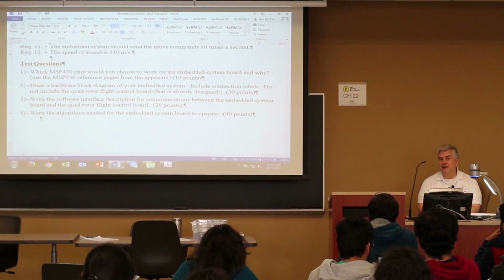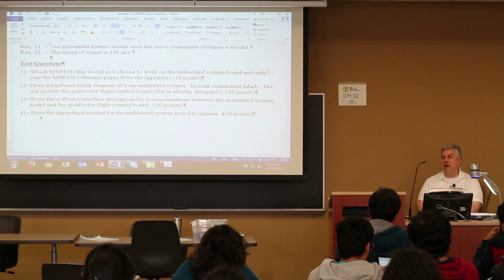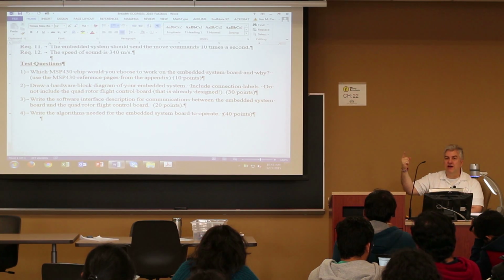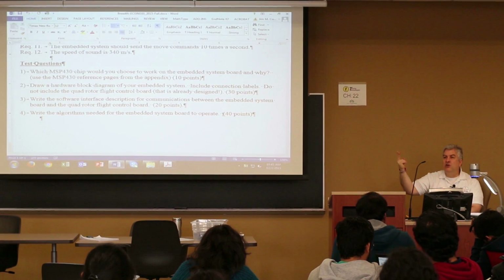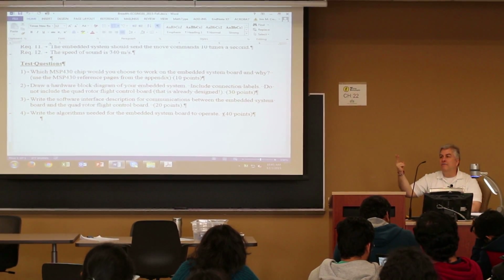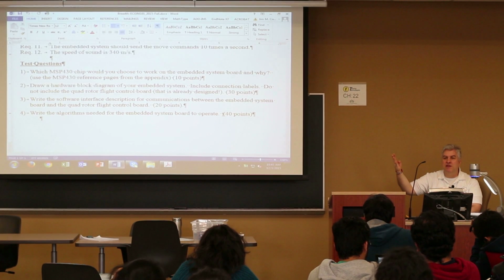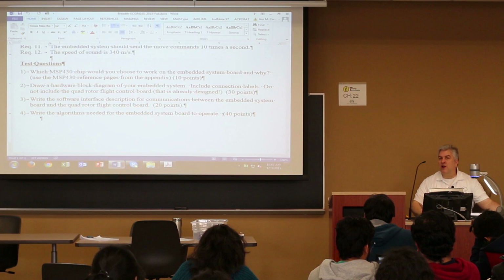So being able to identify what mode you are in. You're waiting for the 0.1 second timer. Then you're in the gather the data state. Then you're in the transmitted the data to the flight controller board state. And then you're in the waiting for a response back and retransmit if needed state. And then you go back to the wait state. That would be a great way.